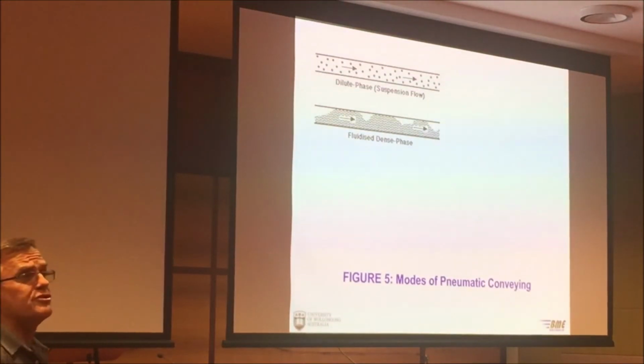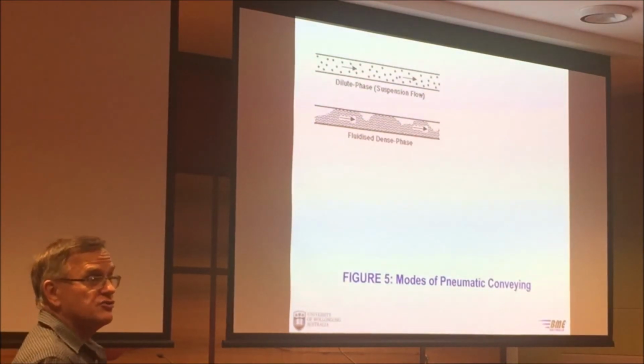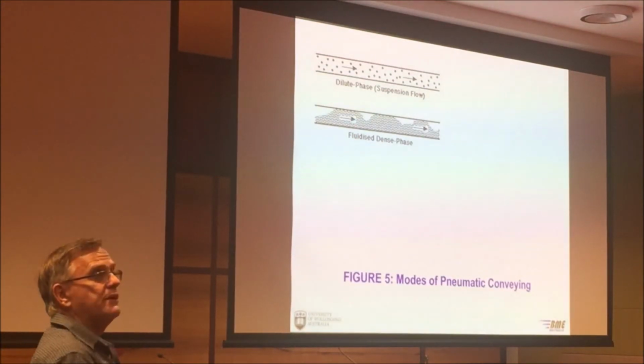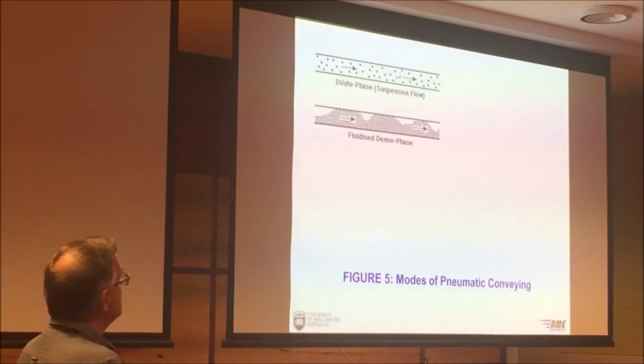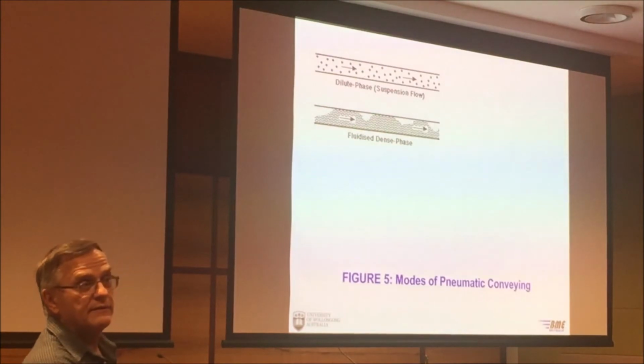But generally with higher pressure. The dilute phase is relatively low pressure, this is relatively high pressure because of the high concentrations. So the pressure drops here are due more to the powder property than the air. So the situation completely changed. The dominant phase here is air, the dominant phase here is your powder, your particle.